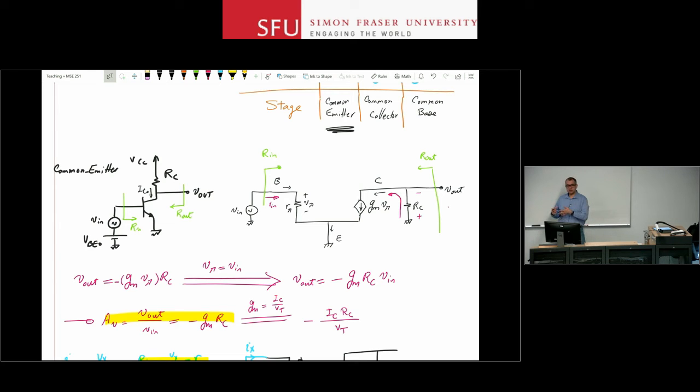Well, you have designed this to be at a stable bias point. The current really shouldn't change by more than a few percentage points from its designed value. And then if you have a few degrees of change in temperature, you can have a few millivolts of change in VBE on, and then that can have a factor of 2 or 3 change in collector current. Most likely what will happen is that your device will enter saturation or cutoff because of those changes. We don't want that, right? So one solution is to go and add a resistor to the emitter terminal.